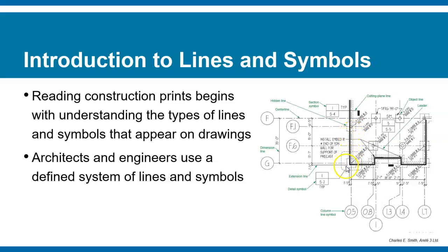So that particular line that I'm pointing to is the outside of the foundation or the footing. So you can see when the footing gets to corners or at certain key points, reference to these lines here, these column line symbols. You've got columns, and then you've got symbols that, see, these are also column line symbols.